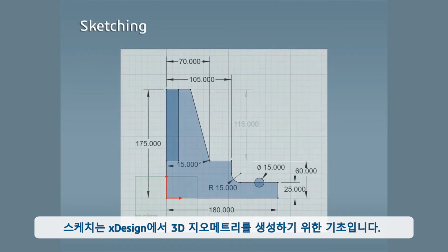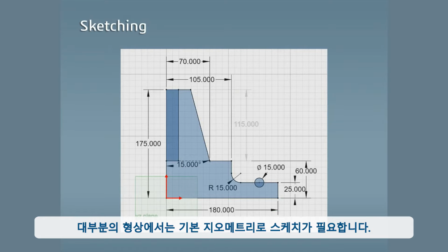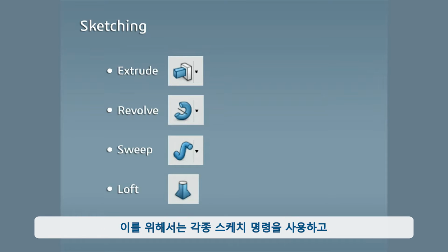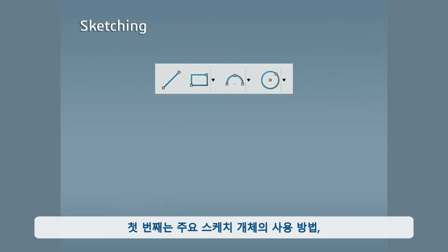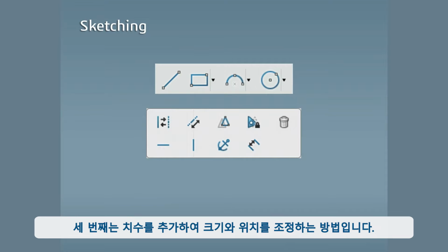Sketching is a foundation to creating 3D geometry in XDesign. Many features require sketches as the base geometry, including the most fundamental features such as an extrude, a revolve, a sweep, or a loft. This makes it extremely important to know how to use a variety of sketch commands and relate them together properly. In this lesson, I'll focus on three separate aspects of sketching: using the main types of sketch entities, adding constraints between sketch entities, and then adding dimensions to size and position them.